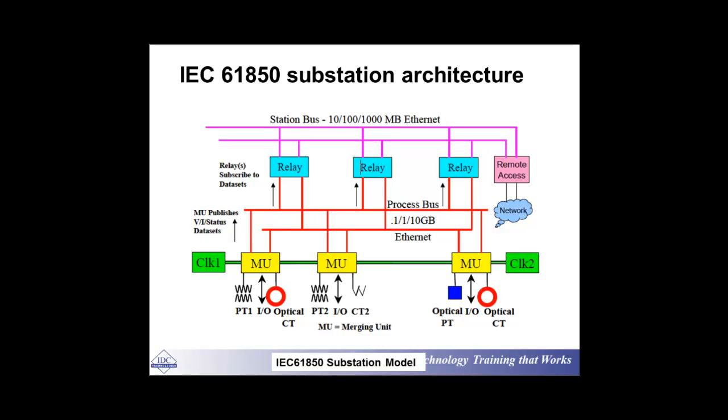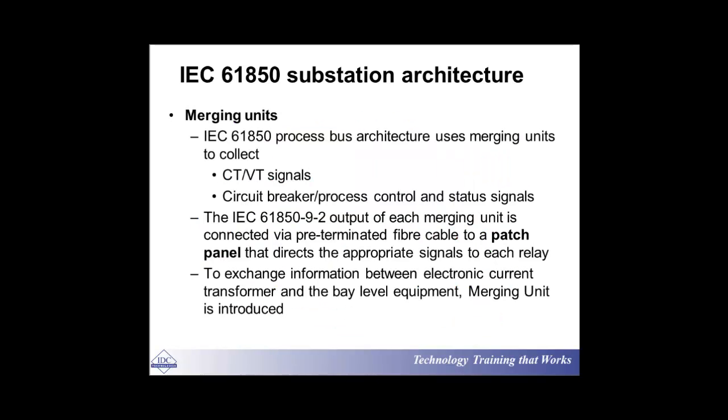So you are going to automate the substation, is that right? So these merging units merge this information, put them in different categories and appropriate groups so that you can then identify and again assemble together or just get them separated. Okay, and then one layer up, it will go to IEDs, let's say relays, and after that you have got the station bus. By means of a network, you can also provide remote access to operators and decision makers somewhere else. So this is the model that we have got for the substation automation.